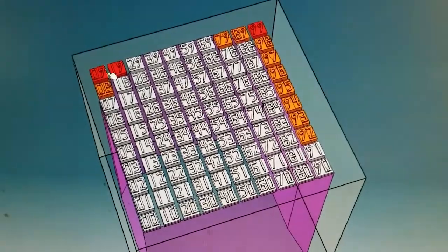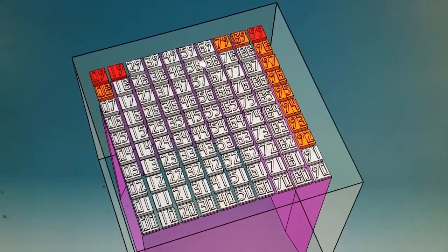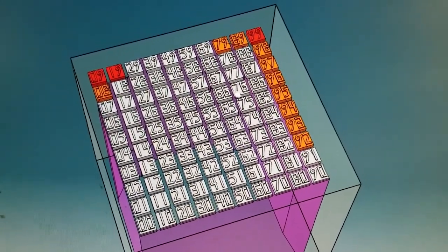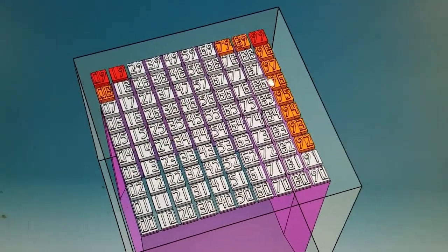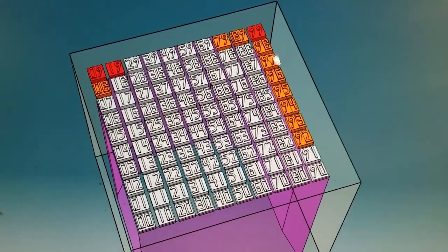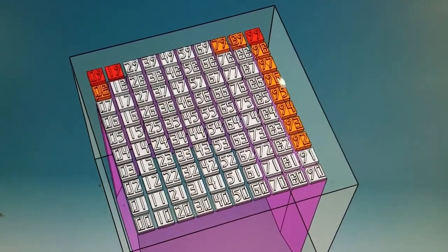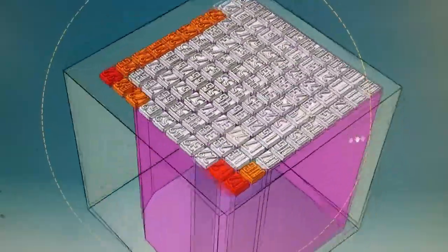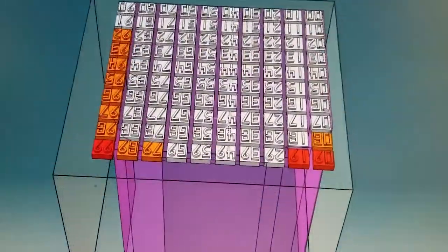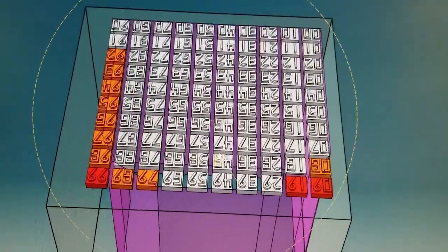Red were areas that just didn't sinter at any temperature, and there was nothing I could do. Orange were areas that had either slight curling or just areas I don't want to deal with. Also, I had some delamination issues along these 90s here that were on the side. The bed actually is arranged this way. It's kind of backwards. I should have modeled it differently in Catia.